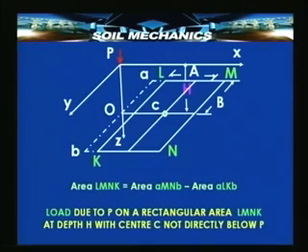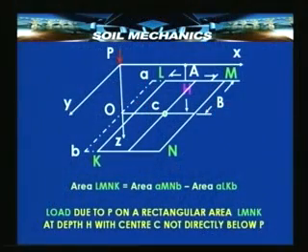Now, here in this diagram we have taken C on a line parallel to the x axis, but in general it need not necessarily be on a line parallel to x axis. The rectangle could be even rotated. We nevertheless have to divide this into equivalent rectangular areas, and by using appropriate geometrical addition and subtraction, we should be able to get the total load on any desired area.